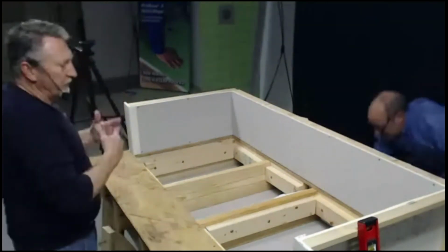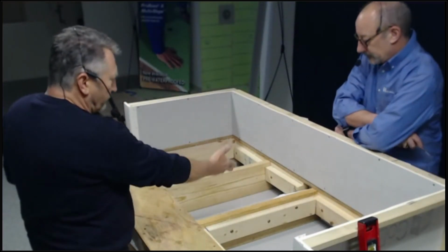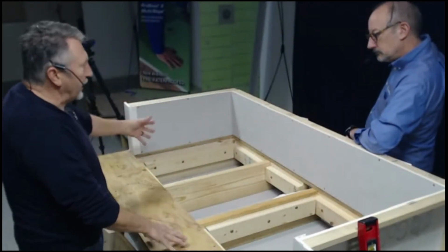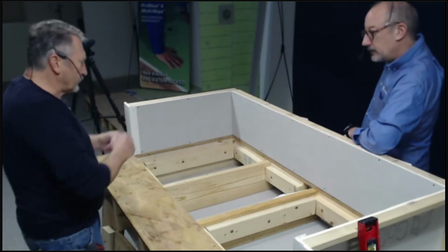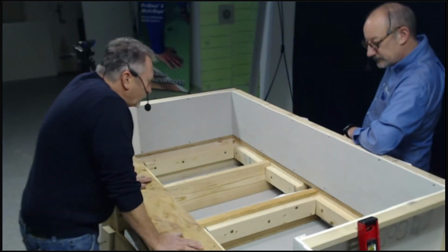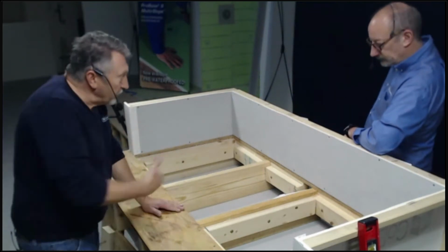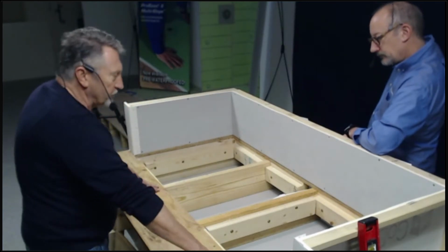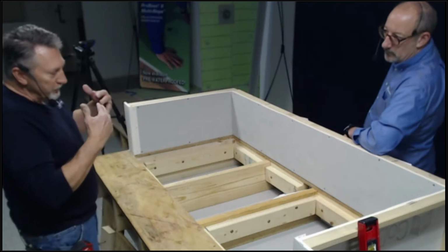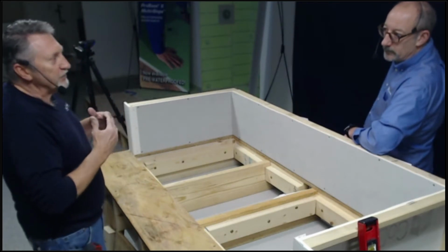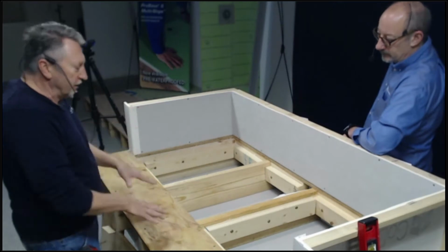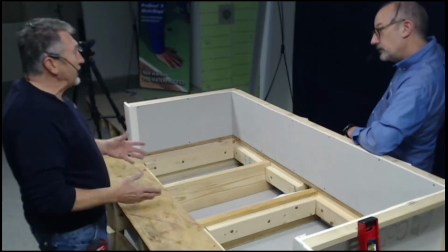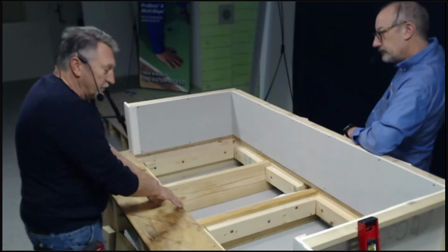Okay. So now I've exposed all my floor joists. You can see the rough-in plumbing is there. Yep. Now, for time purposes, I've got most of my blocking already in. So I'll demonstrate how I got to that point. So first of all, with my blocking, now that I've cut my tongue and groove substrate away from my dry space, I always have to worry about the deflection here. Because when you tongue and groove all this together, it basically makes the floor all one piece of plywood. It locks it in. You don't have the deflection between your floor joists. Right. But I cut this out, now I've eliminated that. So I have to worry about my deflection right between the floor joists.